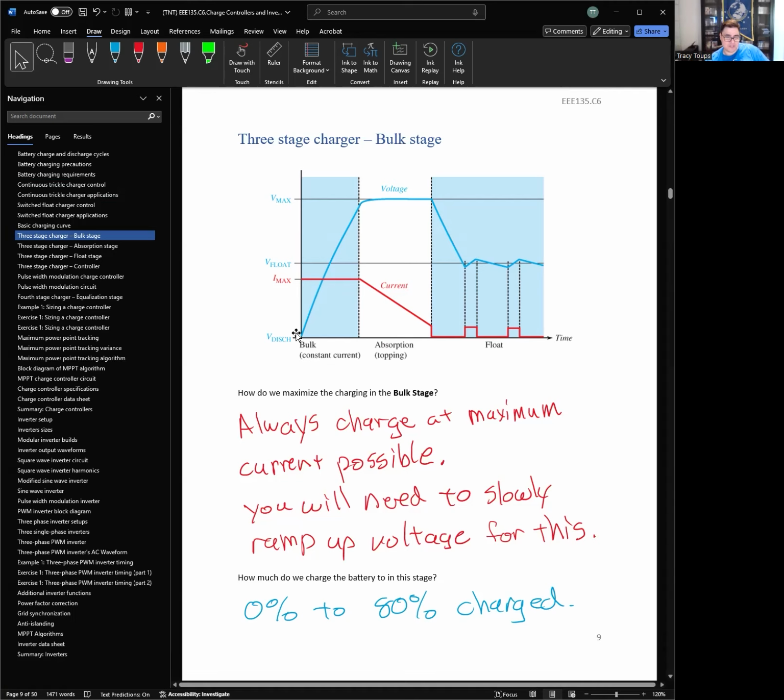Okay, so that's why you see the voltage is constantly moving up. It's keeping up with the internal battery voltage rising as it gets charged. Okay, so that's a constant control system where we need to monitor the voltage consistently, or actually we monitor the current. If we see the maximum current starting to dip, we could pop up the voltage to bring the maximum current back up a little bit. So just to make sure that main current, it might be wavering up and down, but we need to make sure it's as constant as possible.